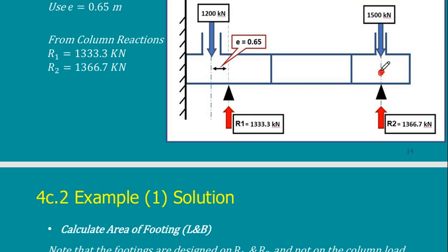If I take the moment at this point, what is the arm of force of these two forces? 0, because they pass through this point. If I take the moment around a point and I have force coming through this point, then the effect of the moment here is 0. Then I end up having only these two forces.